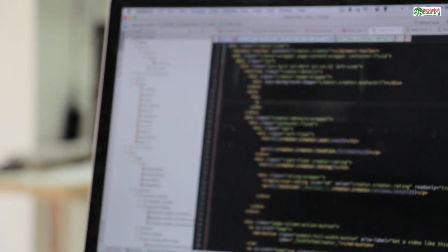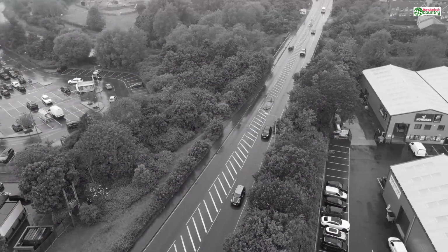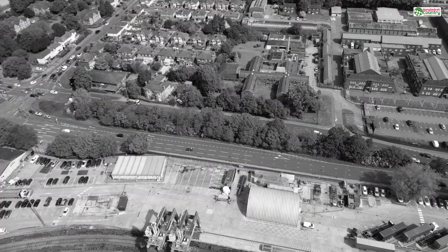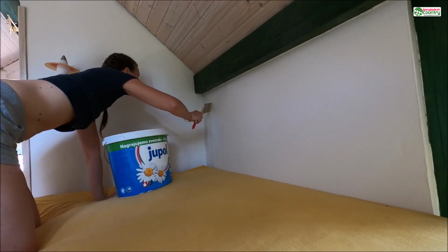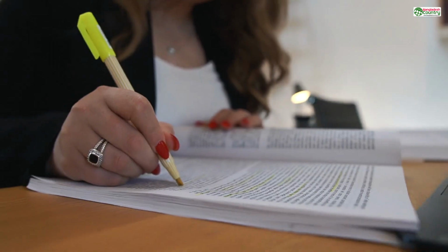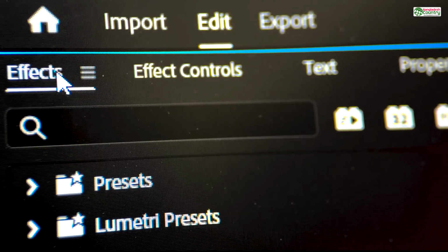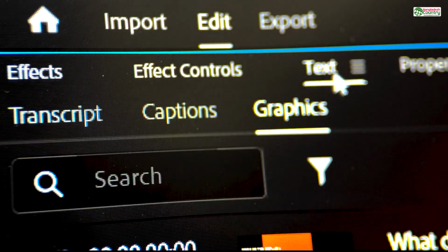Areas that are safely above the minimum will show up as green. Areas that are getting dangerously close might show up as yellow or orange. And the critical problem areas, the walls that are thinner than your 1 millimeter rule, will be highlighted in bright red. There it is. No guesswork. Your software is now pointing a giant red arrow at every single part of your model that is destined to fail. Your job is now simple.